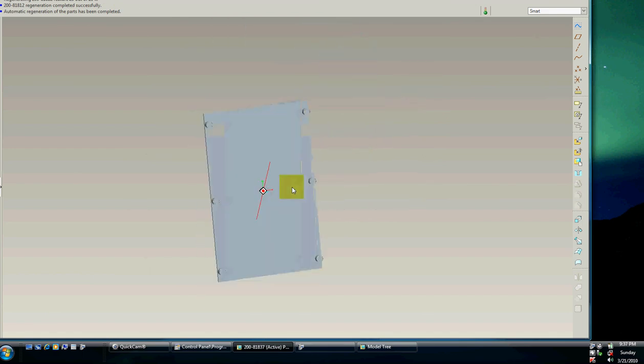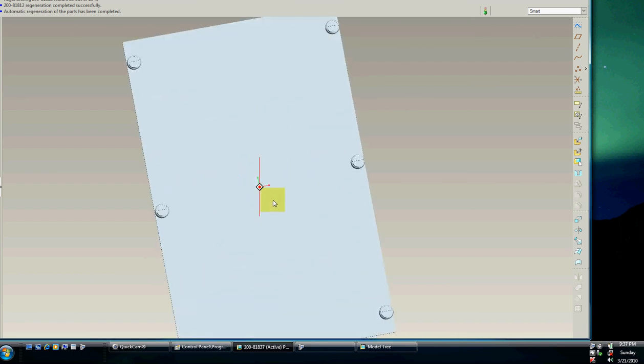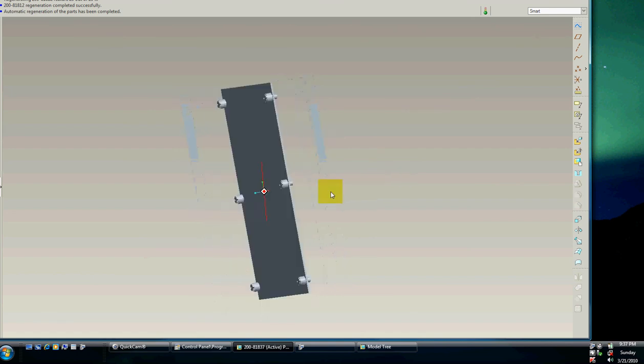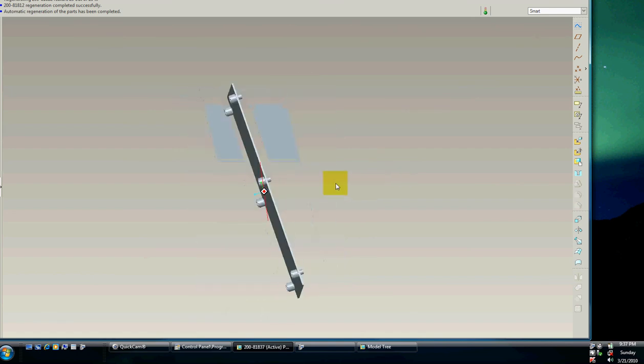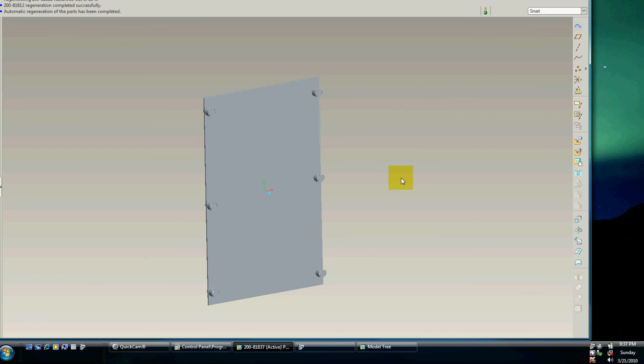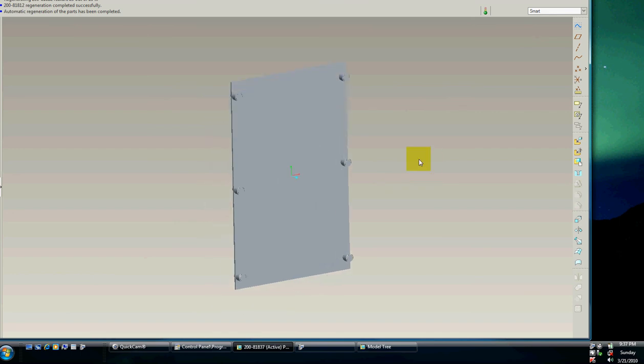So again, I didn't have to spend any time modeling. It's very, very parametric and can be changed at any time. If I had this, like the Zeus rail, in an assembly and did a save as, and in the second assembly this had to be different, I could simply regenerate it to the proper dash number, and I'm done.